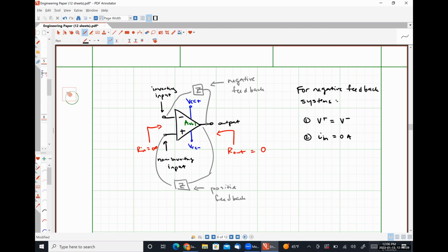So this is because the extremely large voltage gain in a negative feedback configuration makes the differential voltage, the voltage that's measured between the non-inverting input terminal and the inverting input terminal, effectively 0. It's not truly 0. It really winds up being somewhere on the ballpark of a few microvolts, but it's close enough to 0 for us to not care. And no current can flow into or out of the input terminals of the op-amp because of the extremely large input impedance. Okay, so it took me a little bit over 2 minutes, but this is very, very basically how op-amps work.